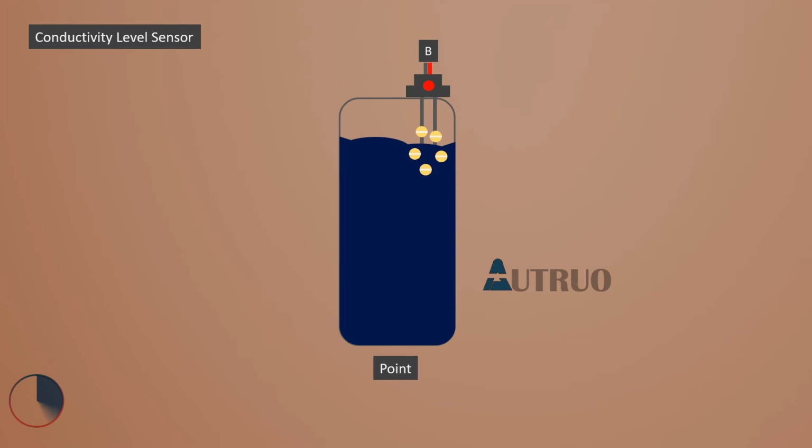Finally, the third setup. That is sensor C. It is a multi-level sensor which can be grounded by the tank by having two probes at the same length. The tank will not need to be grounded. Each probe will complete the circuit in reference to the longest probe, allowing multiple liquid levels to be detected on a single sensor.